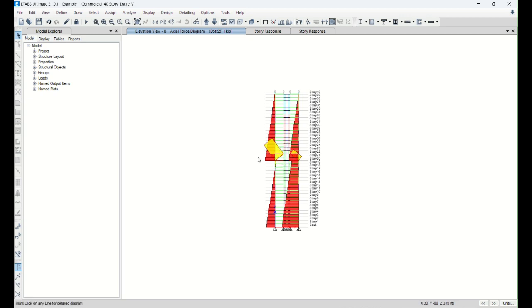Still, we have some kind of issue with our gravity loads because the bracing is holding up, so we underestimate our actual forces, right? If we use this model as it is, obviously we may end up under-designing the column. So one thing is, we design the column due to the gravity load.